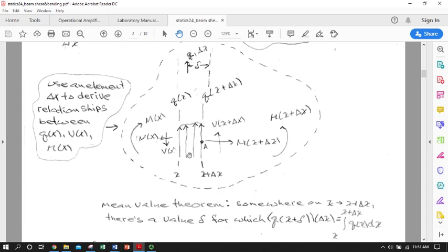So let's just tally up those forces here. Being contributed by the now missing left-hand side of the beam that we cut away, we have a shear force V acting at x, and V changes with x, but this is V at point x. We've got a tensile force, axial, represented by an N at point x. Who knows how that varies, but we know at point x it's N at x. And then likewise we have a moment, which is M also at x. So notice everything is relative to the location on the beam in the x direction.